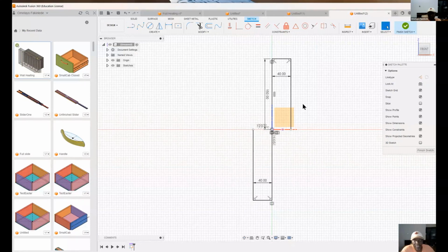here. So these lines are solid black, and that tells you that the lines are fully defined. But because we want this to be part of the path of a copper pipe, these sharp edges are not desirable. Because they are not desirable, we can solve that by using filleting. So we can create a fillet at this angle here, and let us say we put that fillet as 15. Okay, so that's a 15 fillet. We use our marking menu by right-clicking the mouse and repeat that fillet. We do the fillet here, and it's again 15.